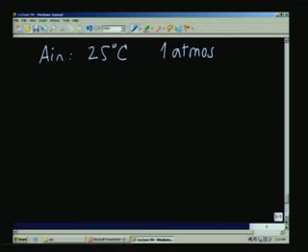What I am going to do is describe a typical situation and find out the typical values of the velocities I am going to measure, and then accordingly we will find out the suitable instrument for measuring the delta P. So, I will consider air as the flowing fluid at 25 degrees Celsius, because the flow rate is dependent on the density, and I will assume that it is at 1 atmosphere, with very small difference with respect to 1 atmosphere, because delta P is there.